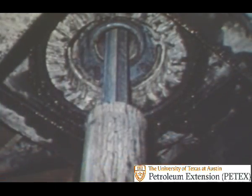From underneath the rig floor, we can see the bottom of the rotary table with the square Kelly extending down through the rotary and into the bell nipple. Notice that the top of the cylindrical bell nipple is flared to catch any mud that may spill out around the rotary and run down the Kelly. Often a bell nipple with an even larger flare is used. Once the mud is in the nipple, the mud is returned to the mud system and not wasted.